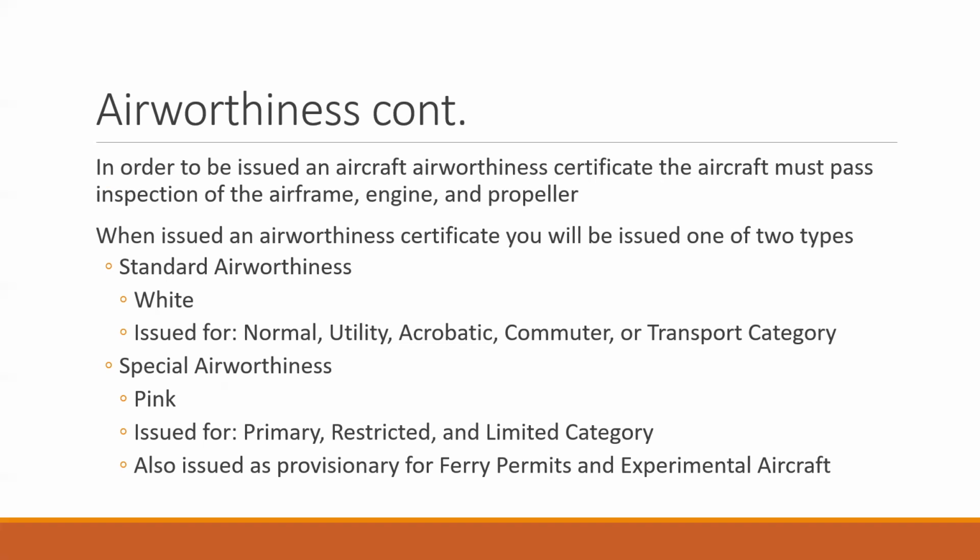And these airworthiness certificates, just like your registration certificate, have to be displayed inside the aircraft in a place that either the crew or passengers can see. So, not hidden away in a book somewhere underneath the flight desk. They have to be somewhere in normal sight of somebody other than the pilots.